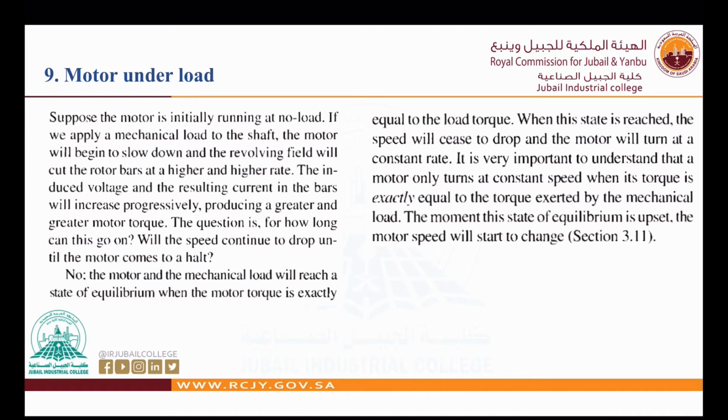So it is very important to understand that the motor only turns at a constant speed when its torque is exactly equal to the torque exerted by the mechanical load. So when the induced torque from the motor and the load torque are equal, then we have a constant speed.